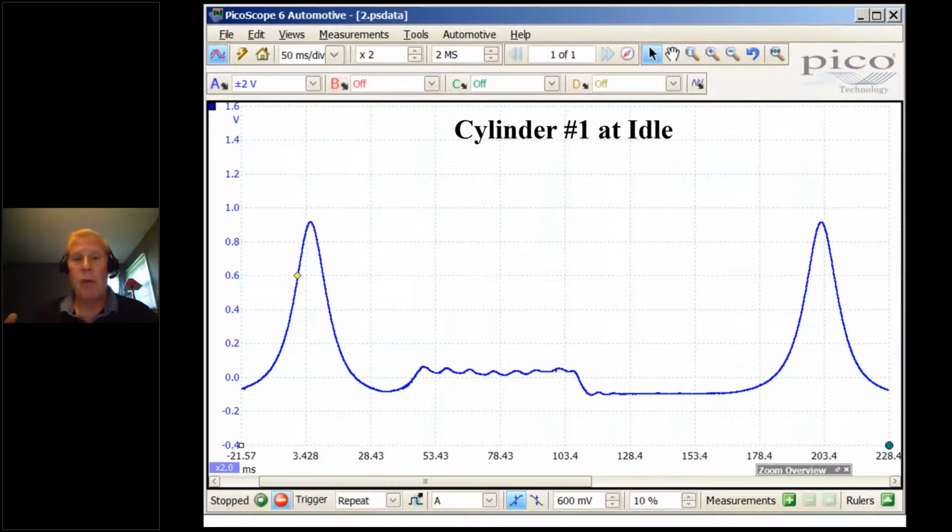Now, there's all sorts of ways to check for restrictions in the exhaust. A conventional way has been to pull an O2 or drop the exhaust. I'm not going to necessarily argue against that, but at the end of the day, the restriction in the exhaust causes a problem for the cylinder. So I'm going to go in the cylinder, and again, I realize this can be a tough engine to pull plugs on, but if I can pull the plugs, I'm going to go in the cylinder.